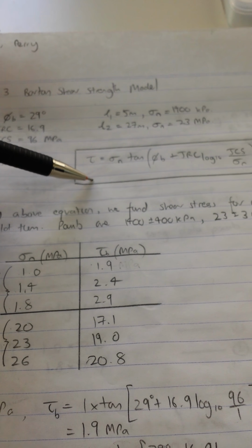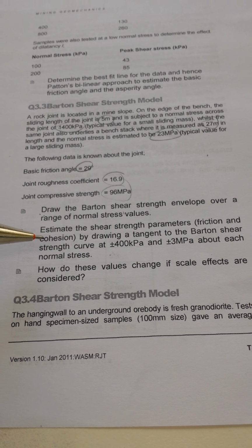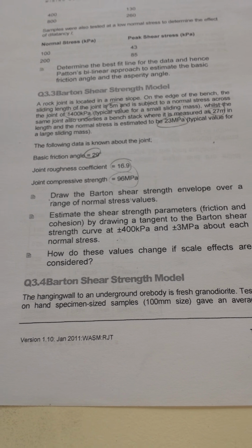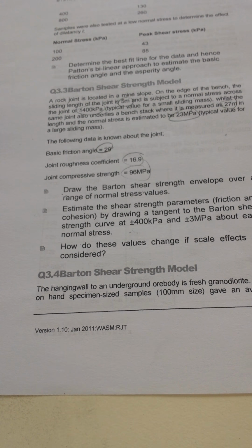I plotted it in Excel. Looks something like that. There's the equation of the line. So that's the first part done. Second part of the question, estimate shear strength parameters, friction and cohesion, so that's like the Coulomb parameters, by drawing tangent to the curve at each of the normal stresses. I'm not really sure what it means by draw a tangent curve, but you can solve it simultaneously just from